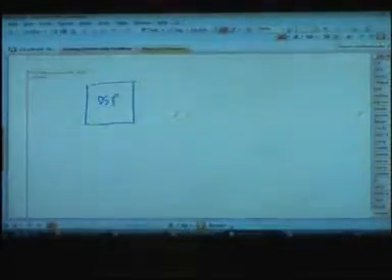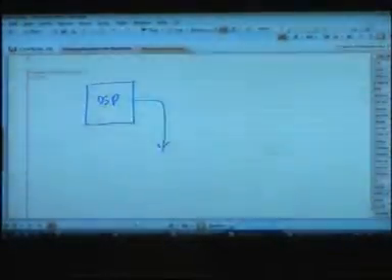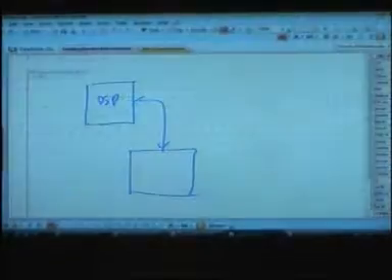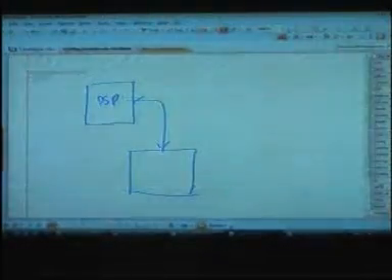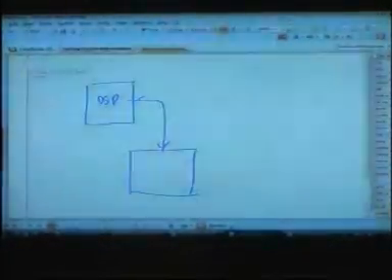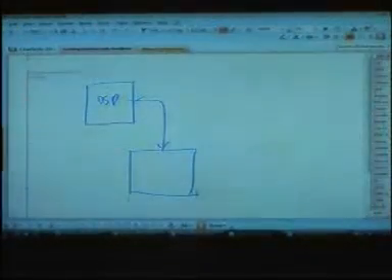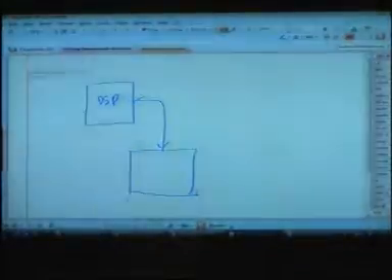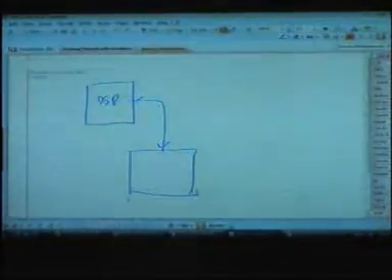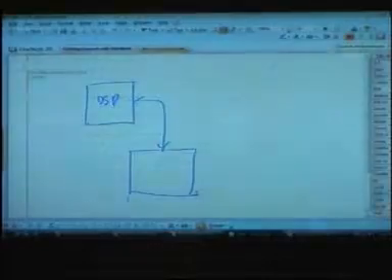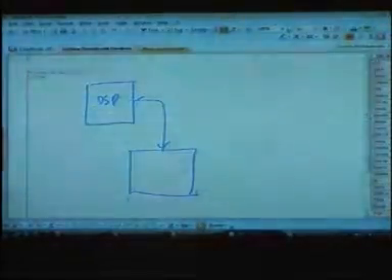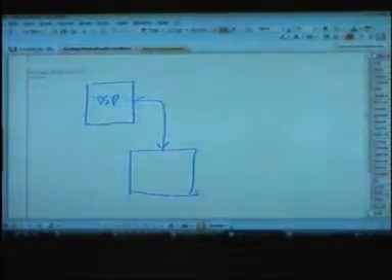For example, if you have a device, maybe a digital signal processor, talking to another device on an interface, there are very stringent protocols that you need to adhere to in order to make something go from one device to another. You need to send a request, and in so many cycles you must get a grant, then you get the bus, then you do this, you do that. So at RTL level it is very complex to model or to design the interfaces.